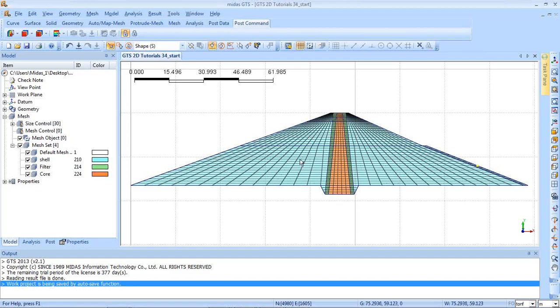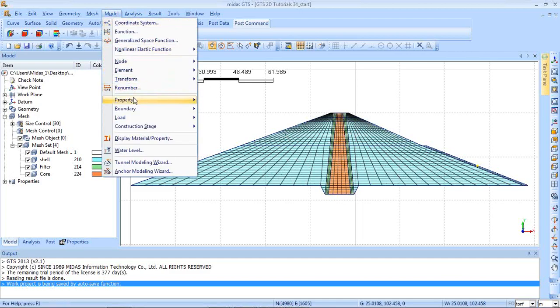So we have defined, so just to summarize what we have done till now is that first of all we have defined the unsaturated material property, then we have gone for the map meshing considering the KH area, and then we have defined the boundary conditions for nodal head like flood water level, then the drain boundary condition, and finally the seepage phase boundary condition. Having defined this, since we also have to perform the slope stability, we have to define the ground support condition also.